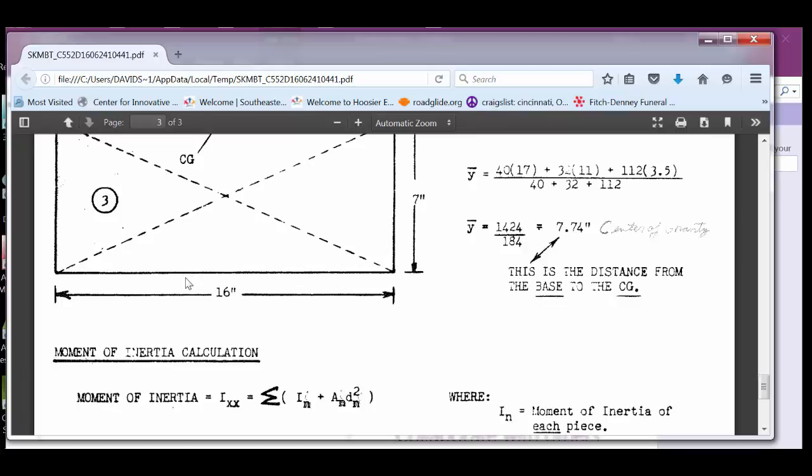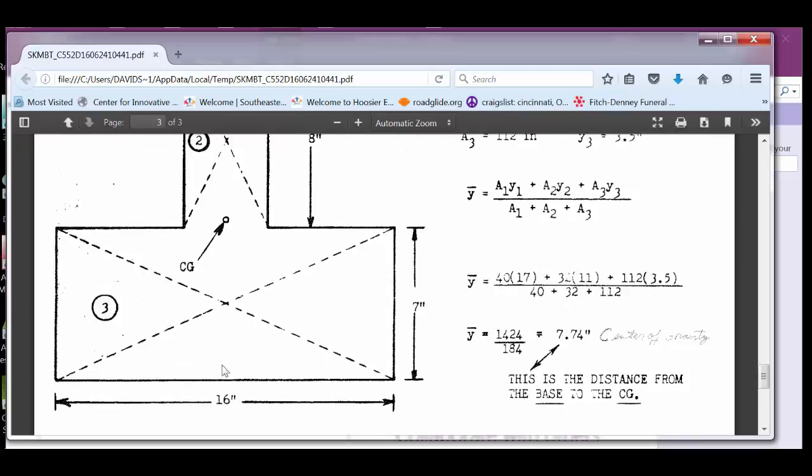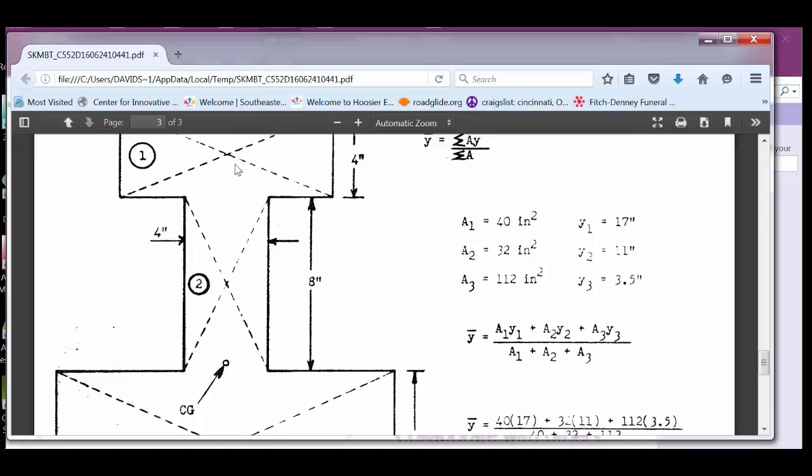Yeah, because you can say the x-axis can be anywhere. Now, typically, we make it at the bottom of the overall composite, right? That's typical. But you can make it anywhere you want, as long as you tell them how far it is away from something in that composite. So if something was suspended, then that x-axis would be at the top instead of the bottom. It could very well be. Okay? So that's why you add those 2 up plus half of this one.